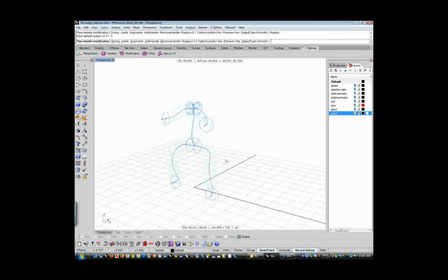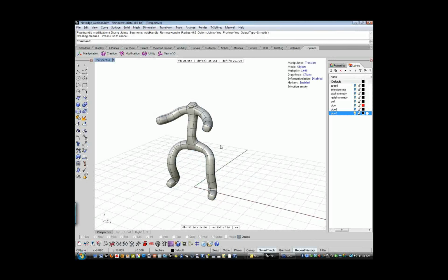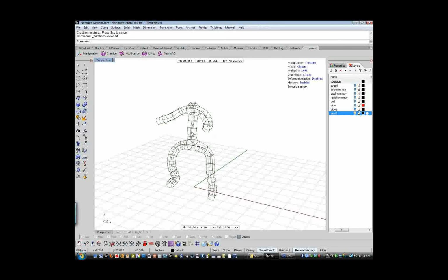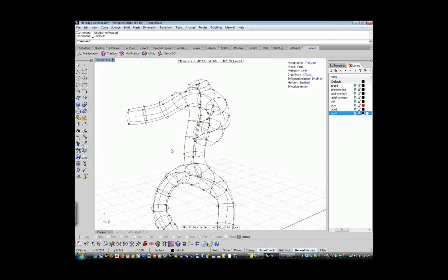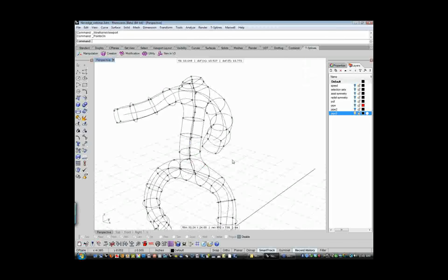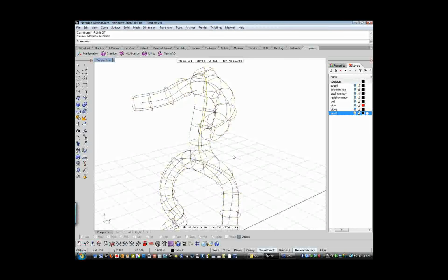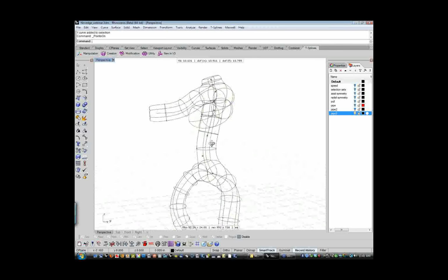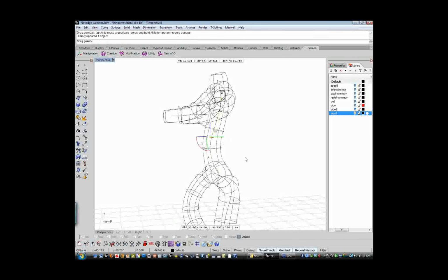If you can go ahead and change the radius. One other thing, you can change the radius on those existing handles. We did show that, yeah. But right now Kyle has a T-spline model, and as long as you do not move the T-spline's control points, if you turn on the control points of the curve, you might want to exit the T-spline mode so that you hide those T-spline control points. So just turn on control points only on that curve. Then you can drive the T-spline by moving these control points. As you drag that, you can see the T-spline will update.